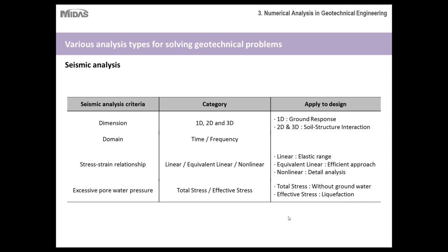And then excess pore water pressure. When groundwater levels are taken into account for a seismic analysis, you would need to account for effective stress as well as liquefaction, and then total stress to analyze certain parts that don't have groundwater present. So these are all things to take into account for seismic analysis. I won't go into too much detail yet, but later on, I believe one of our courses is dedicated to seismic analysis. We'll go more into detail on how these parameters are used specifically for numerical modeling.